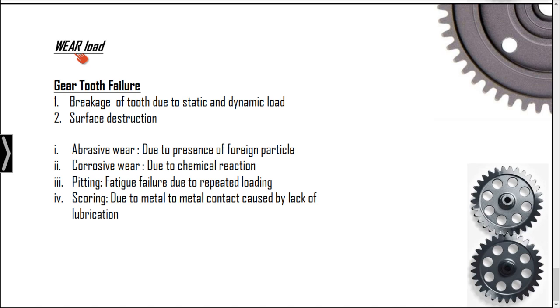Like we said, the static load, the Lewis allowable bending stress, the second one the dynamic load, and the third one the wear load. These three are the major types of load which have to be considered and used for the design of a gear. So the design is purely based on these three types of loads.